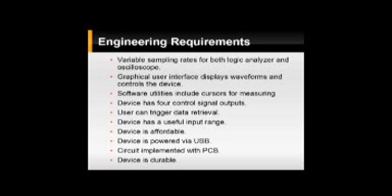We will now discuss the engineering requirements for our project. There must be a variable sampling rate, where the logic analyzer has a maximum sampling rate of 8 million samples per second, and the oscilloscope is required to have at least a 700,000 sample per second sampling rate.